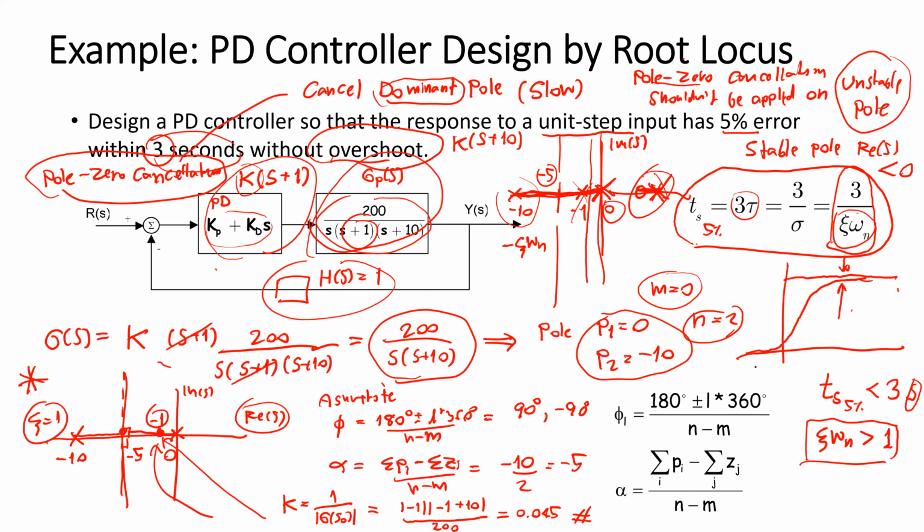Wow, lucky. Okay. The analytical way is like this. You read the problem, you try to apply the technique of pole zero cancellation from the PD control. You check the system need, the time constant depending on the settling time, and you can know how fast the system you need to design. And don't forget to confirm the damping ratio by the requirement of the overshoot.